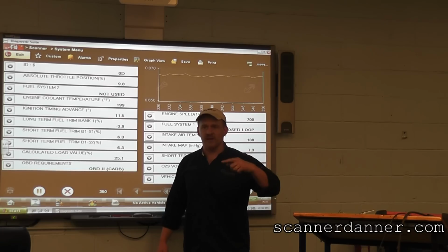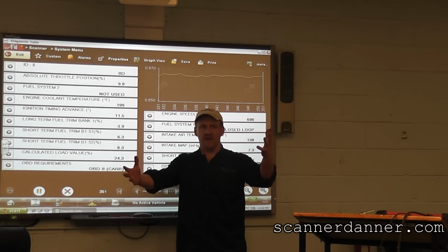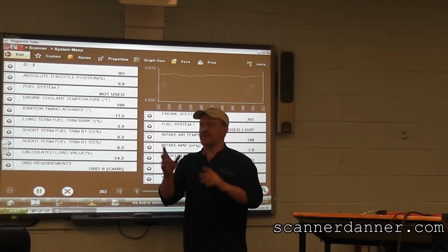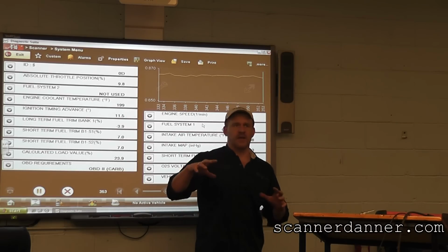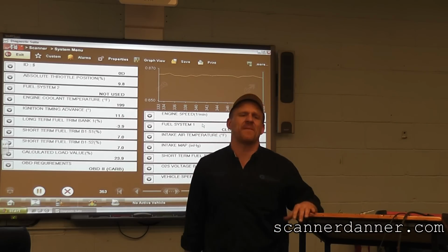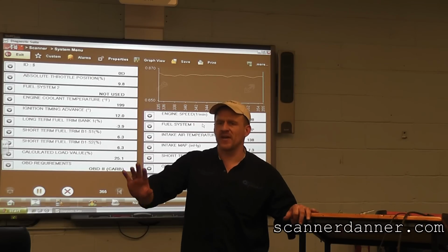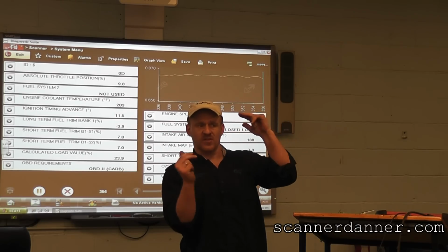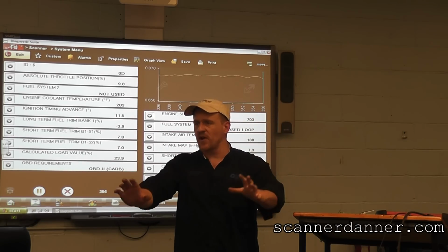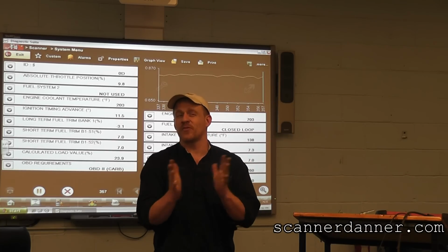Our total trim, and what I told you, there's a variable to that. And I'm saying that variable may very well be the downstream trim is a factor in the weightings of these, if that makes sense. It's not critical for troubleshooting. It's just an observation that using the counter fuel trims to say this car is fixed might be a variable to that. I think I've known about it all along, just never really thought about it.